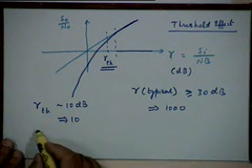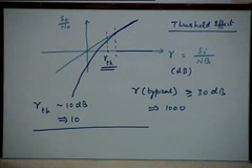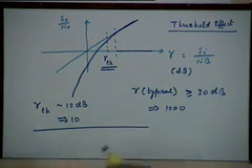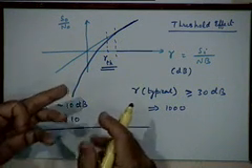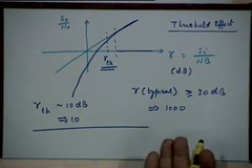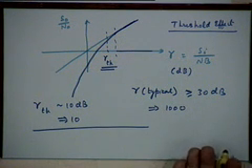So that's a point of comfort, that fortunately for at least broadcast kinds of applications, we can still use the envelope detector. What was the motivation to use the envelope detector? The motivation was to simplify the receiver, but at the same time we don't want to lose in performance. This says that you will lose in performance, but fortunately that loss comes in those regions where it is not important. We are not going to use those regions at all in typical applications. So it doesn't matter, the simplicity can still be kept without much loss. That's the lesson that we learned from this.